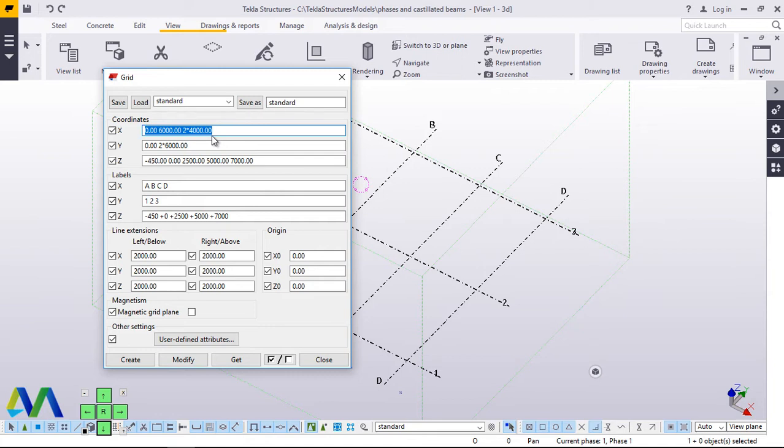For the x-axis, I'll feed 25 columns with an interval of 6 meters. On the y-axis, I'll feed 8 columns with an interval of 5 meters. Then I have here on the z-axis the various heights that I will be dealing with in my structure or the model. My very first height will be 3 meters.